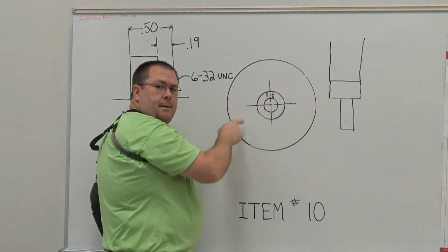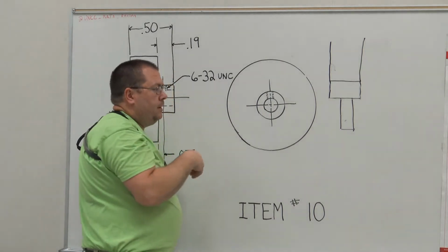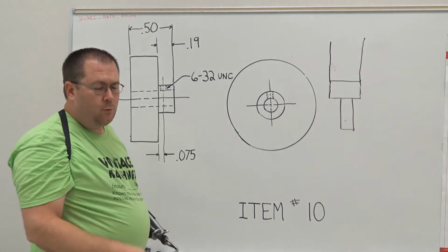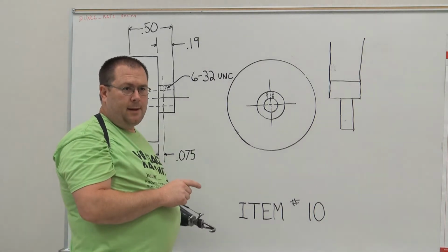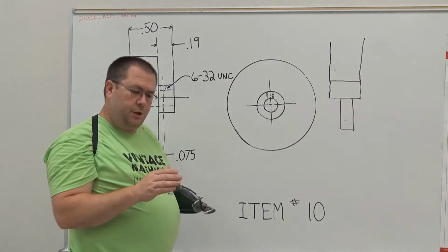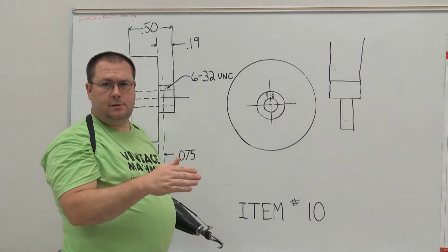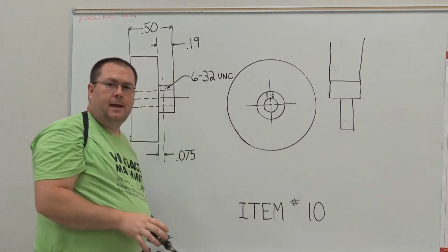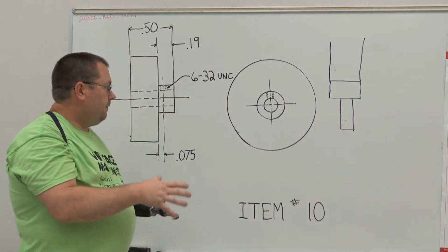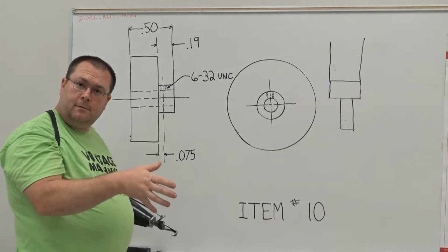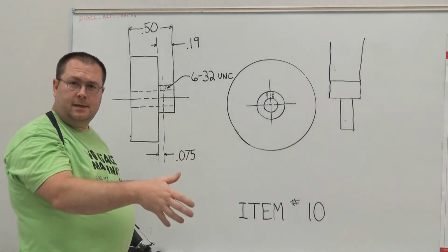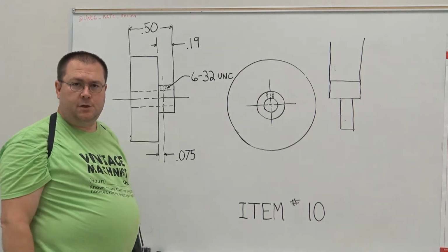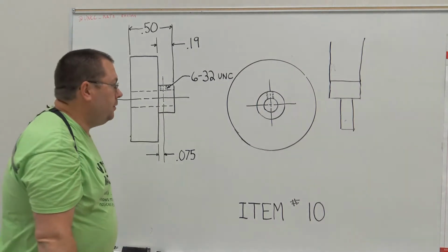But the major diameter of this part has a plus or minus 10/1000ths tolerance. So we have to think, if it's plus or minus 10, which we should know at this point is a relatively loose tolerance, that the major diameter of this flywheel is really not that terribly important. If it measured 990 in diameter, or if it measured 1 inch 10/1000ths in diameter, it's really not going to affect how well this engine runs, okay, when we hook air to it.